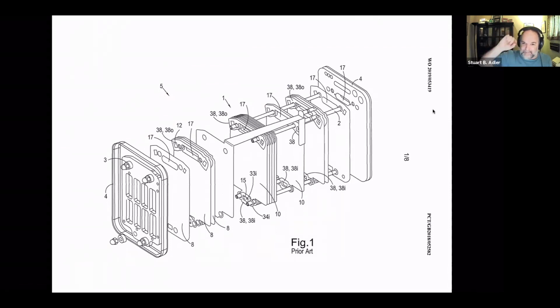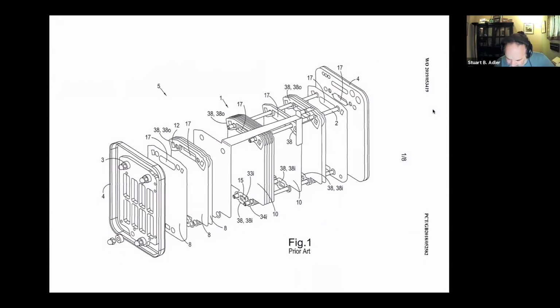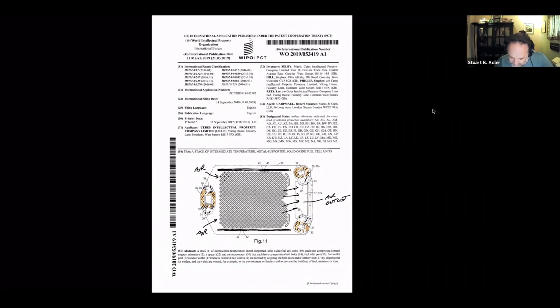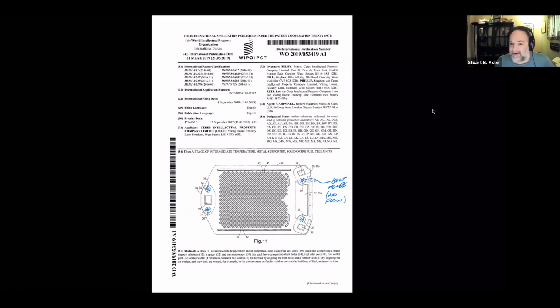So when the whole thing is done, you end up with a series of cells. They're all stacked up. The little gaskets complete and seal up the manifold along the entire height of the stack. And then to keep pressure on it, to make sure electrical contact is uniform and maintained all the time, even though there's a little bit of expansion and contraction, the way they do that is with tie bolts. So they run bolts all the way up and down the stack, and then put on spring-loaded nuts on the top, brings it down and holds it in place. And so that explains the last features on this plate. So these other holes, those are all bolt holes. They don't carry any gases. Those are just holes for threaded tie rods that run all the way through the stack.